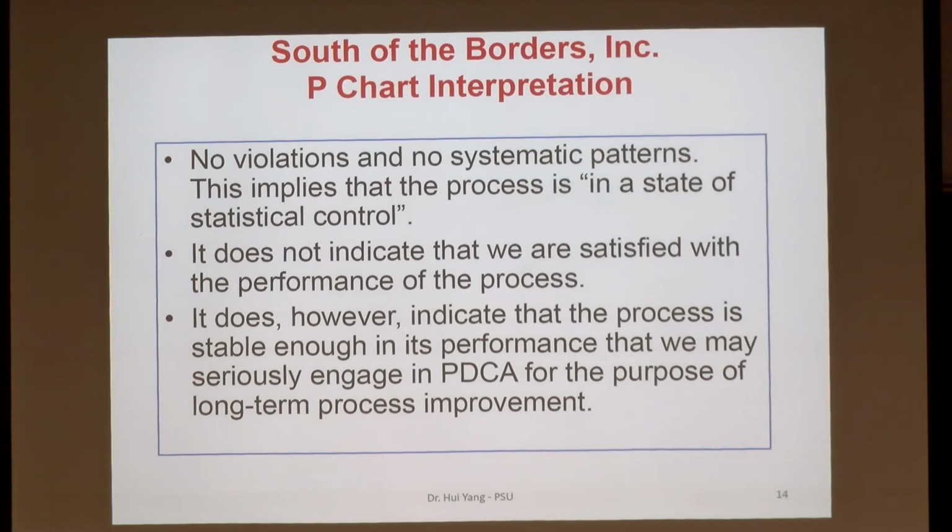So again, what is PDCA? PDCA is plan, do, check, and act. Act means once you check, you find some out of control points, you're going to eliminate the root cause and improve the process.